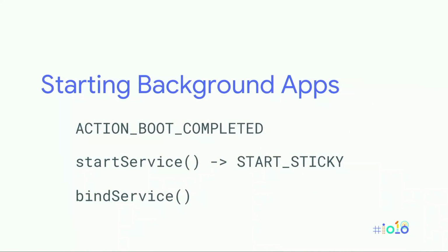The first that you might be familiar with is using the boot completed broadcast to listen for a final boot message coming from the Android framework saying that the system is up and running, so you can launch other apps if you would like. Do not use this on Android Things. The primary reason is those background execution limits: your background services actually can't be properly started into that state. In a lot of cases, it won't even work.